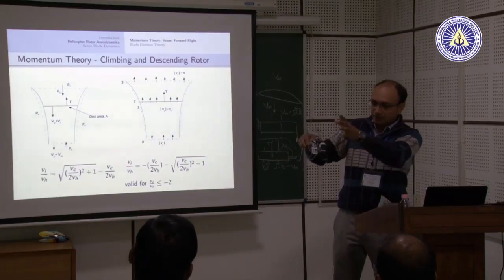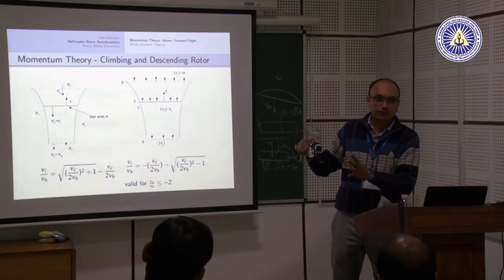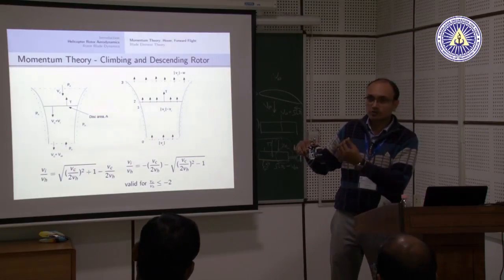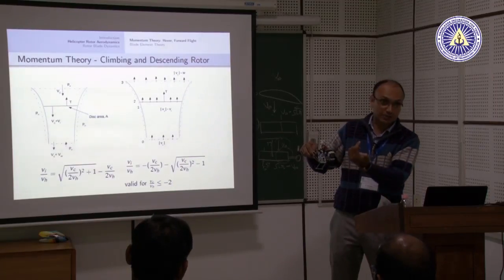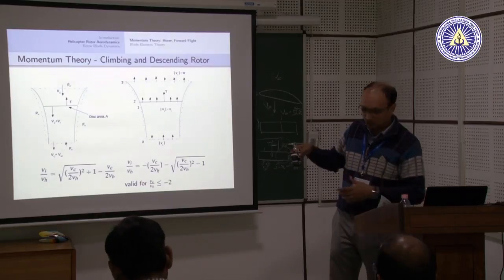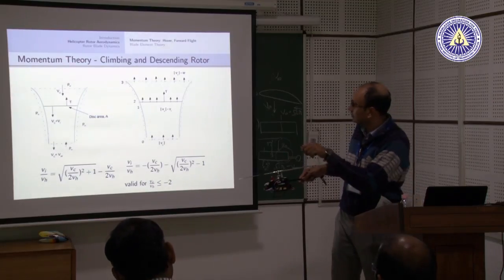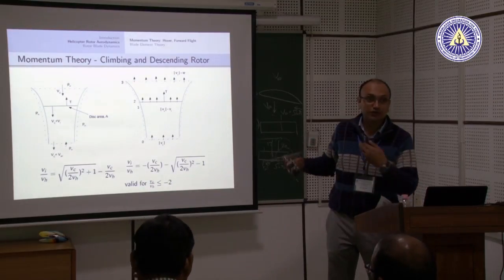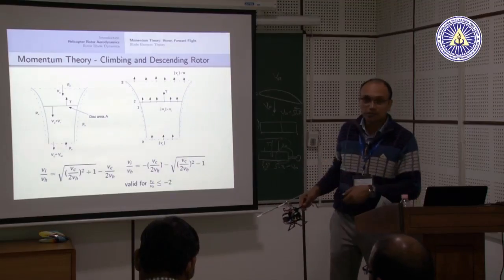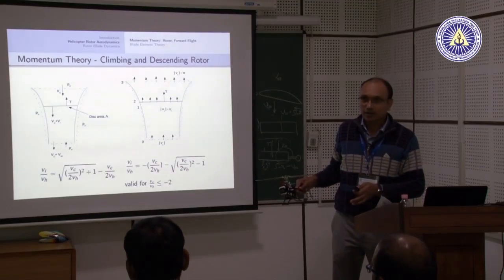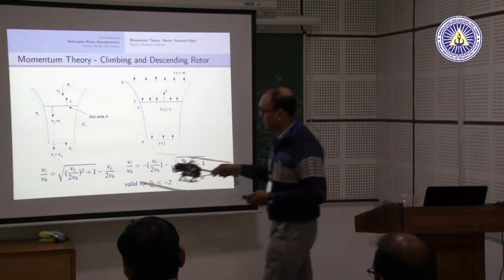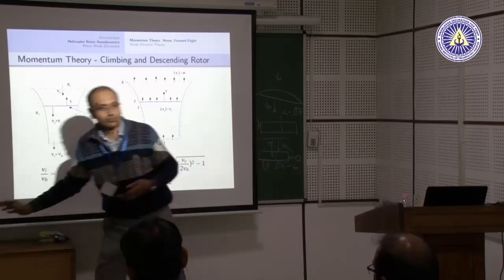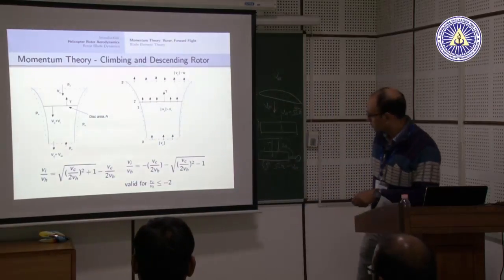So overall there would be locations where the flow velocity may be 0, some places where it is down, and some places where it is up. Then our main assumption that the flow is nice and uniform in one direction everywhere in our control volume is no longer valid. Making that assumption would give you huge error, and as a consequence we cannot apply this simple momentum theory